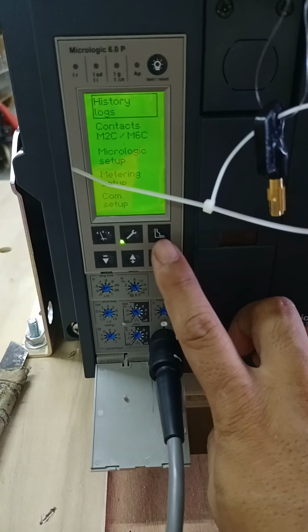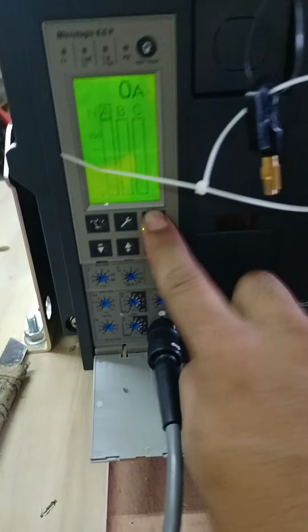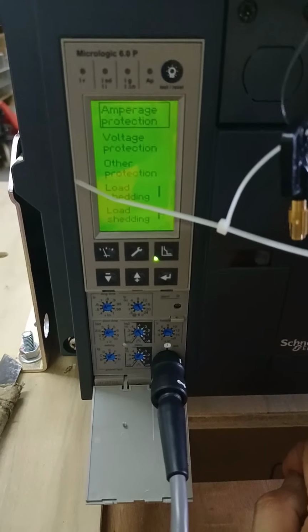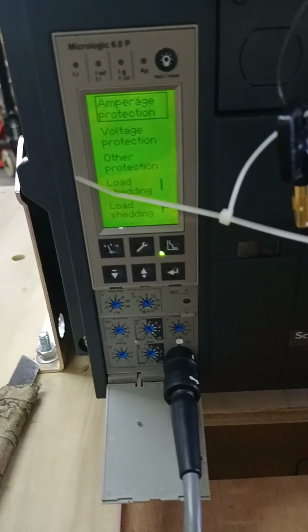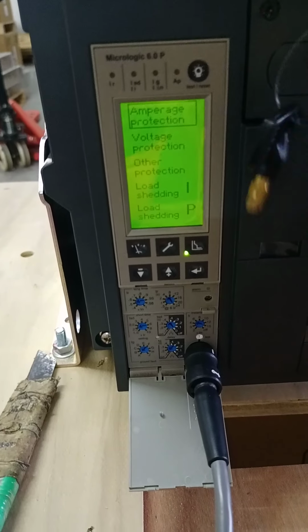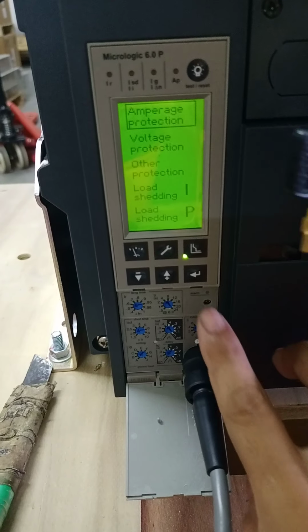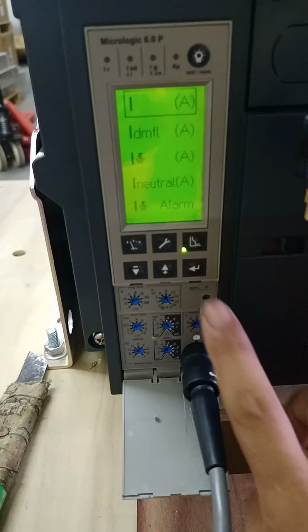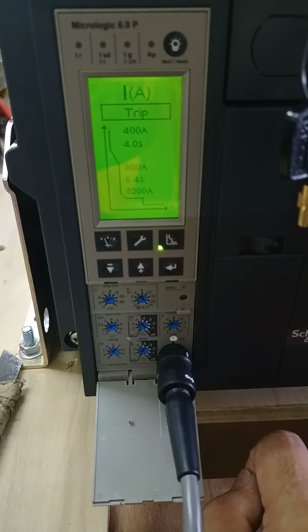Okay. Pressing this third button gives us the ampere protection, the voltage protection, and other protections such as current load shedding and power load shedding. Okay. Entering the ampere protection, pressing this button twice shows us the long time, short time, and the instantaneous